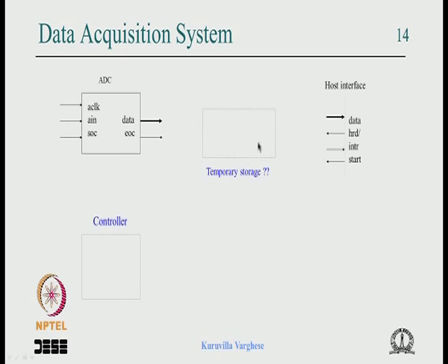Now the FIFO has various signals like full, half full and 3/4 full and all that, okay. If you have a full signal and you connect that to the interrupt, it may be dangerous, in the sense that when it becomes full you give the interrupt, and the CPU has some OS, it does all the task switching. At least it has to, before going to the interrupt service routine, even if it is a simple system, it takes quite a few clock cycles. By the time it comes to read it, it must have overwritten because we are continuously doing this operation. Suppose the host is not stopping it, it will overwrite.